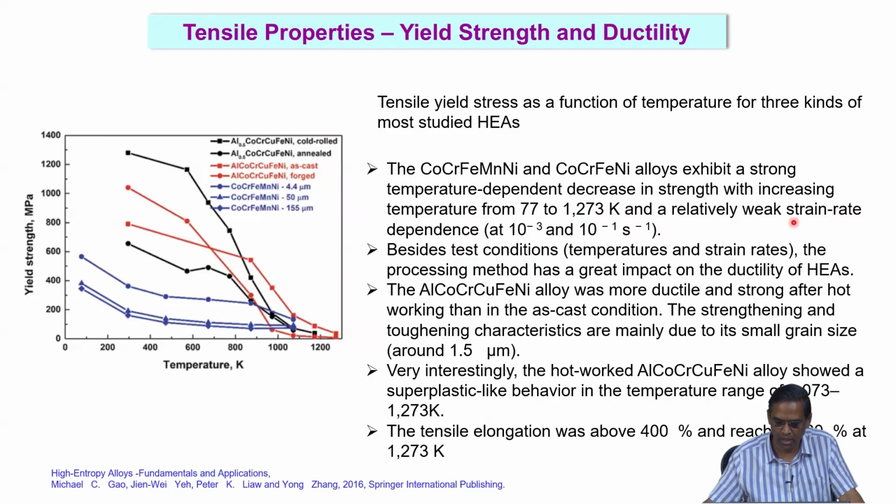Okay, this is very important. The strain rate dependence, right, the material is sensitive to strain rate or not. Why is this important? Strain rate sensitivity. Why is strain rate dependence of the material important? Sure, strain rate sensitivity. It is basically resistance to necking. So, the deformation rate is controlling that, especially at high temperatures.